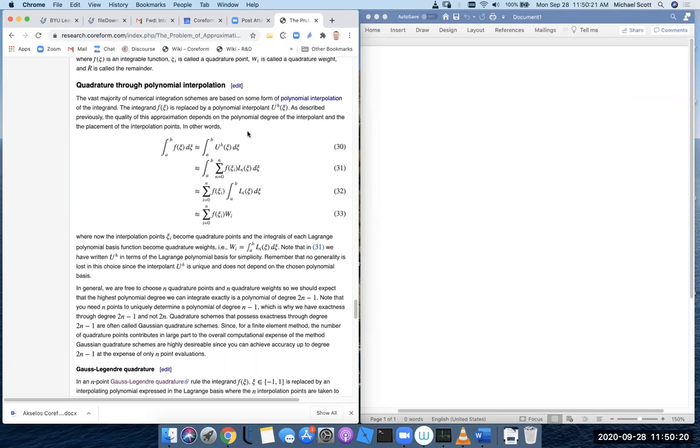Okay, so suppose you're doing a classic locking problem like that membrane locking problem. If you're doing exact quadrature, so you're exactly integrating your shape functions, and you raise the order of your shape function, your locking will go down, correct? Yep. Well, it will go down whether you increase the number of elements or increase the degree. Right.